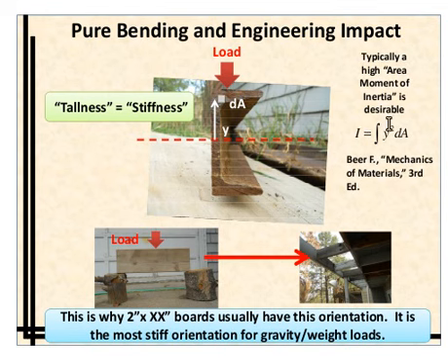Now, you can see we have this y squared term and a dA term. The dA term just indicates a small portion of area, and the y is the distance that area is from the neutral axis. And you just add a whole bunch of these little sums up, and you get the composite area moment of inertia. So what ends up happening is that as you get farther away from this neutral axis, this material out here, you can see there's a y squared, it contributes a lot to the overall area moment of inertia. Whereas material that might be really close to the neutral axis, the y squared term is going to be very small, and so you're not going to get as much contribution to the area moment of inertia.